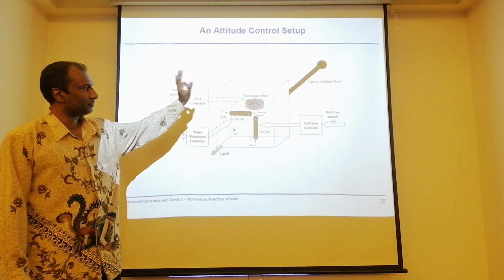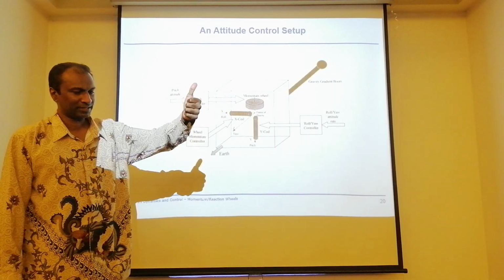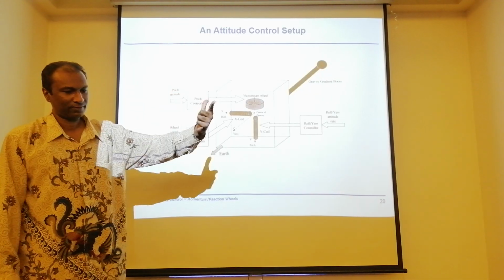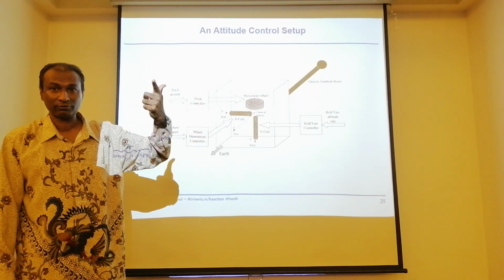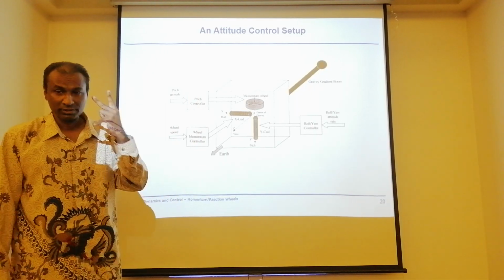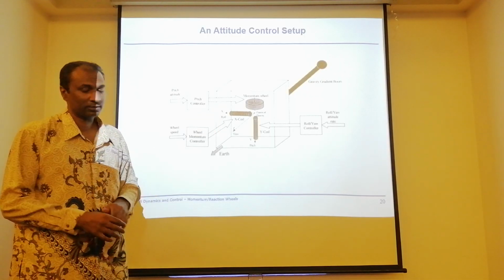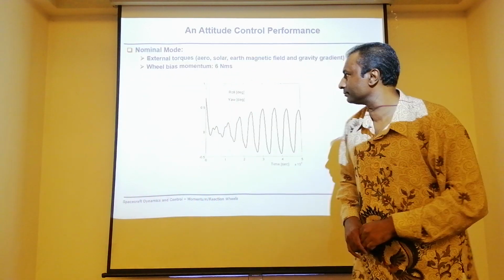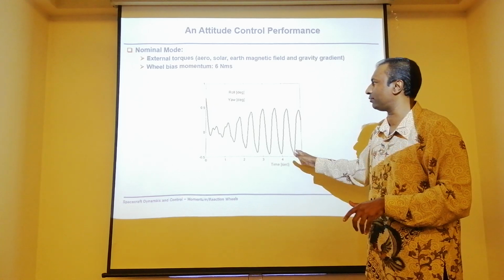You have all those fundamentals. You have passive stabilization, gravitational passive stabilization. You have a very cheap, low-cost way of controlling the satellite, magnetic torquers. You have very good pointing capabilities by having a momentum wheel itself. Okay, looking at the performance here, look how beautiful this performance is.